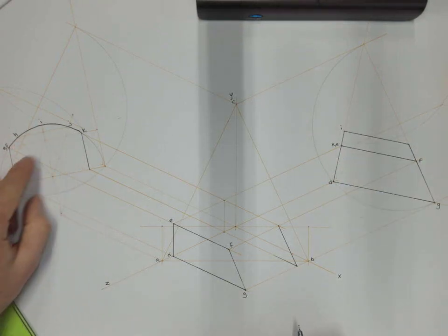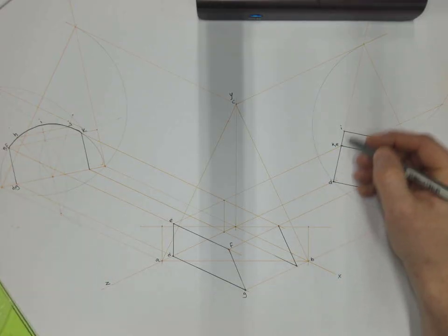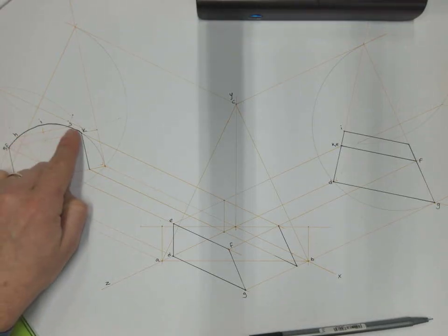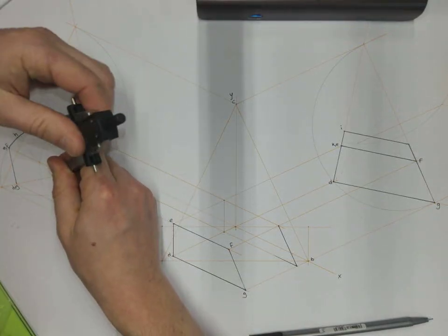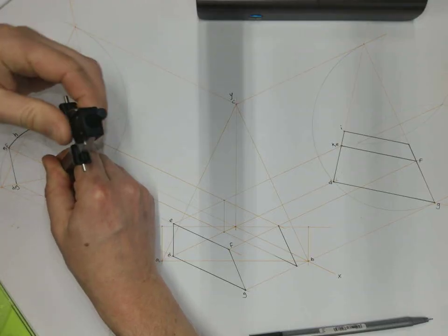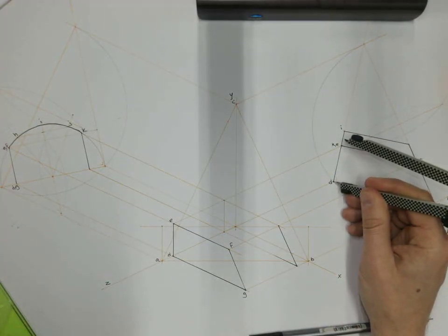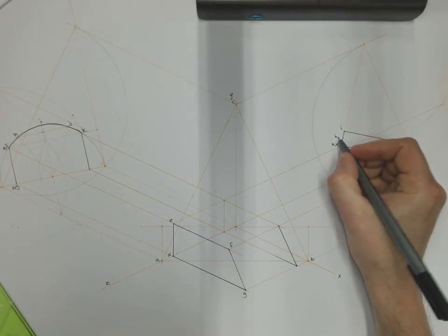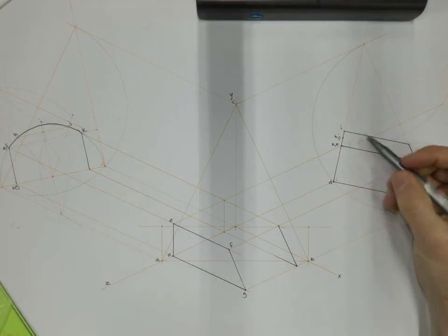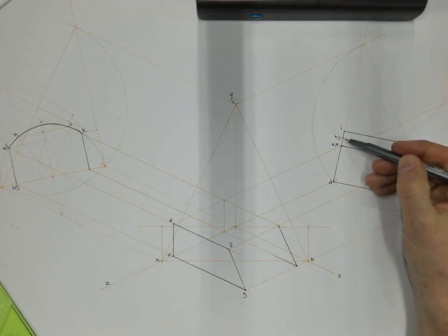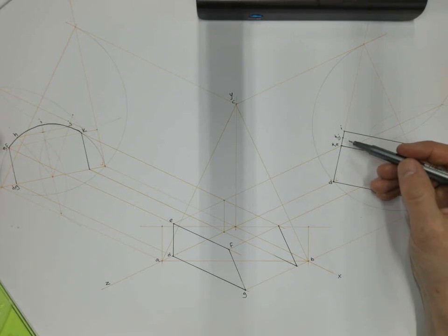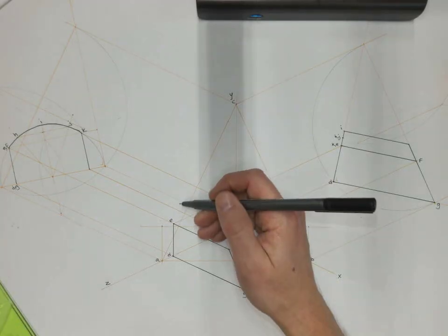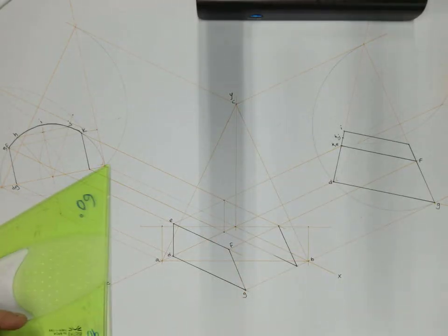So now I need a distance for H and J to apply it to this line in my elevation. So if you draw a line across from H to J, we now have a vertical height for the points H and J. We can take that height on our compass and apply it onto our elevation. So that now means H, J has a physical height in our elevation and points on it. So now I can take H down at the x-axis angle and H down at the z-axis angle to meet, and that's it. Just do that same process with all points.